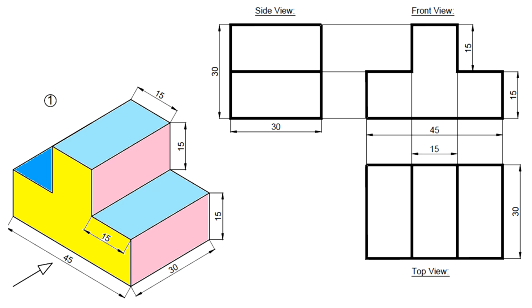When you draw the projections, make the thickness of the object outline up to 1 mm, and these other lines are the projection lines that can be 0.09 mm or 0.05 mm, so very thin lines. Now once you have drawn the front view, you need to draw the top view.